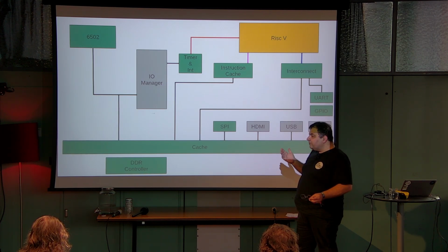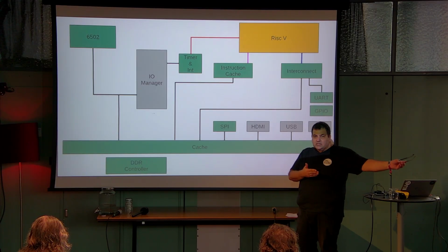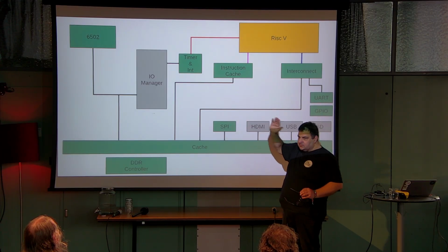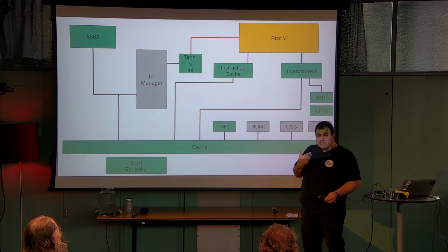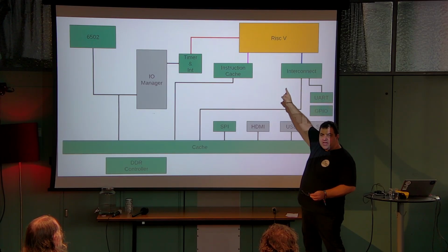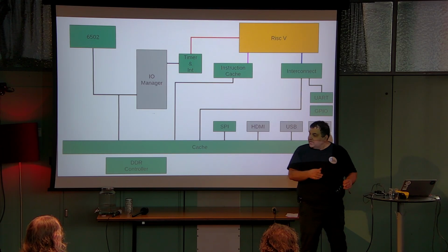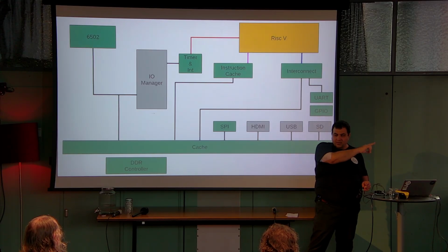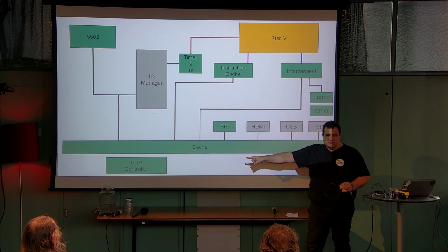And what I found out is that a lot of that logic goes to initializing the DDR itself, the chip. The initialization sequence is very long, and it's a huge state machine. But I already have a state machine in my design. You see up there at the top, the RISC-V? I can do that in software. And then I don't have to pay. And my DDR controller, remember, 4,000 for the MIG, for the memory interface generator. Mine is 200.